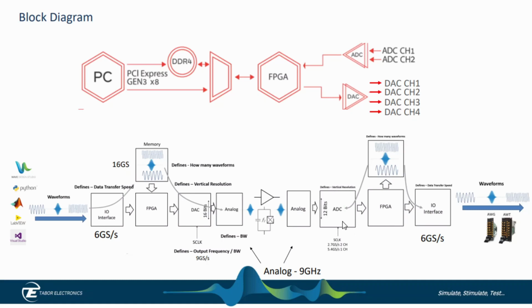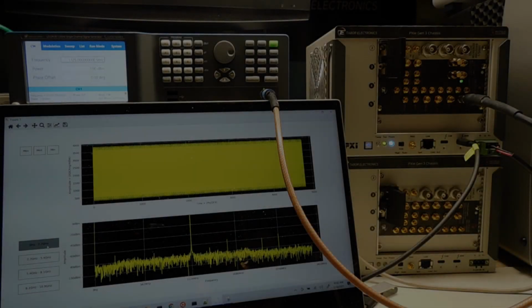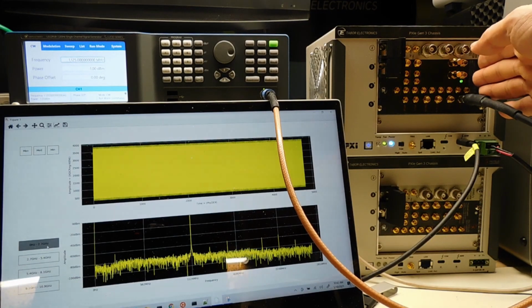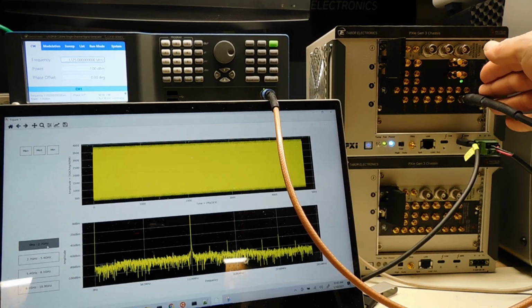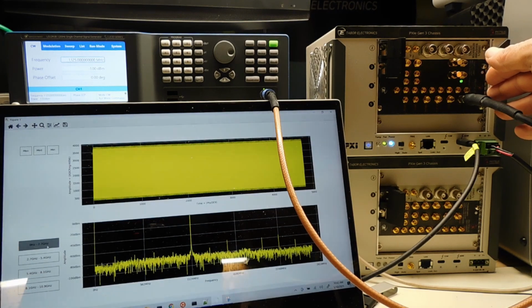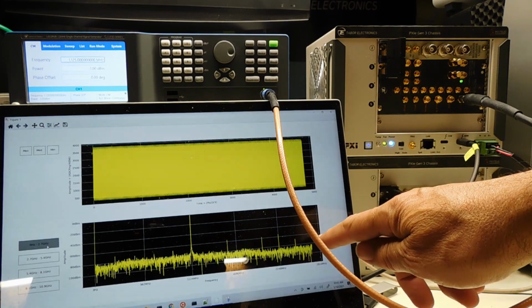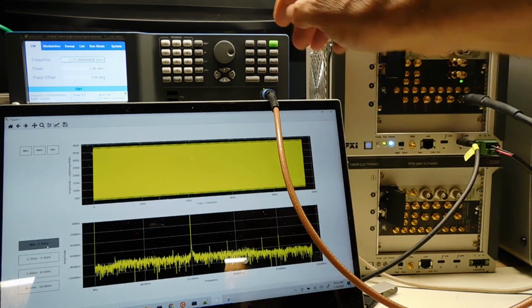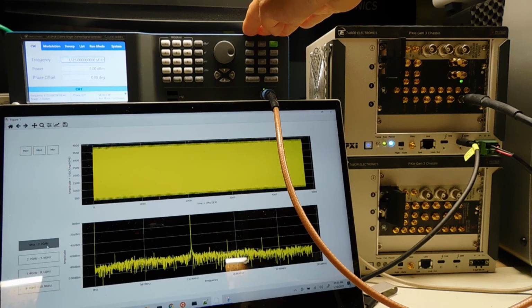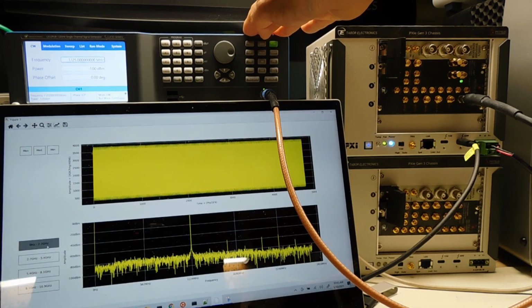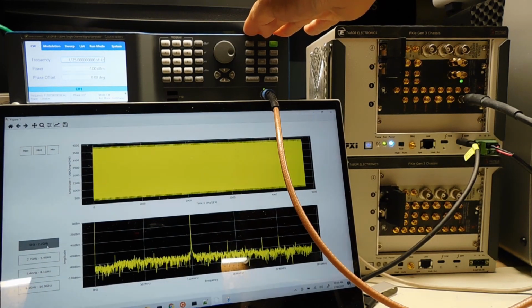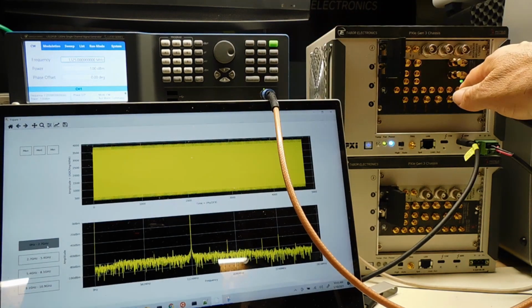And again, we're going to focus on the ADC and how to use the instrument in the multiple Nyquist zones of the analog to digital converter. I'm going to use the Proteus Arbitrary Waveform Transceiver, which we can see here, as an example. It has a 5.4 gigasample digitizer, which gives us an effective digitizing bandwidth of 2.7 gigahertz, which you can see here. And on a signal generator that I've got connected to it, I've got an RF frequency of 1.125 gigahertz at about 0 dBm feeding the digitizer.